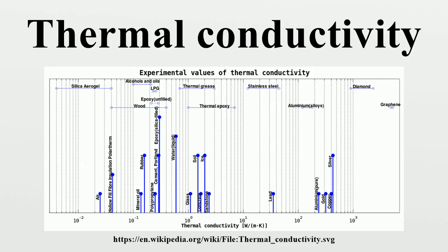A common engineering design problem involves the selection of an appropriate sized heat sink for a given heat source. Working in units of thermal resistance greatly simplifies the design calculation. The following formula can be used to estimate the performance, where RHS is the maximum thermal resistance of the heat sink to ambient, in °C/W. Delta T is the required temperature difference, in °C. PTH is the thermal power, in watts.